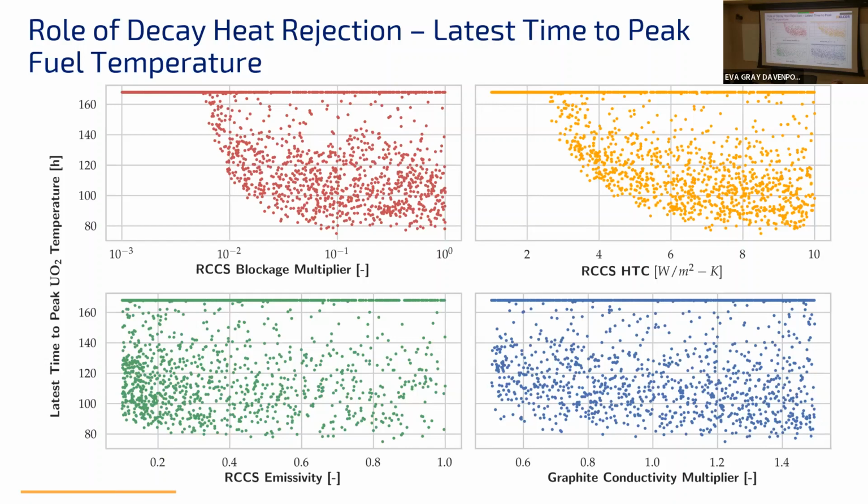One of the things with light water reactor technology is that we have a lot of active systems: pumps and valves. These can randomly fail, and that can contribute to overall failures. It requires you to add redundancy and complexity to your plant to mitigate the potential for that random failure actually having a significant risk impact. Passive systems are potentially really good because they significantly reduce the potential for a random failure, that is, a pump stops working or a pump doesn't start up, contributing to an accident scenario.